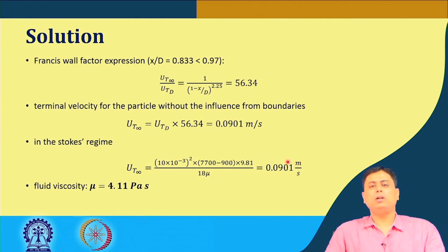The thing you have to remember is that the ut that we mention in Stokes law is the terminal velocity in an infinite pool of liquid when there is no influence of the side wall or the solid boundaries. If you have assumed that the Stokes law is valid, then these things have to be consistent. So that is why, to get the terminal velocity in an infinite pool of liquid, we had to come through the correction factor of this measured value.